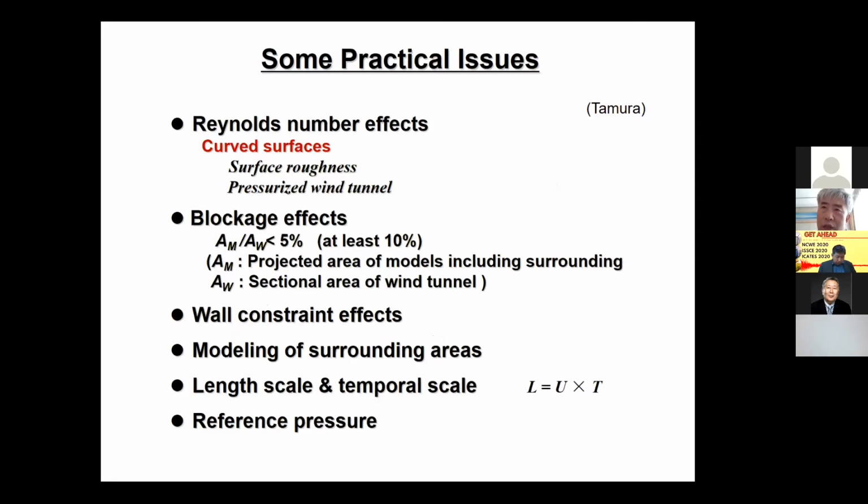But if you have a rectangular cylinder, because the separation point is fixed already, the Reynolds number also has an effect on the attachment point. But anyway, the separation point is fixed. So possibly the Reynolds number effect is not so obvious as in the curved surfaces.